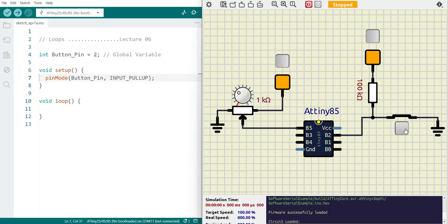So on the other side, if I press, that means this GPIO is going to be pulled low by the switch. It's no longer high. So when I don't press, it's high. It's very important actually to analyze this before you even write the code, right? So when I press, it goes low. So that means us detecting a low on PB2 indicates someone has pressed the button. Do we get the point? So I think that brings it out properly.